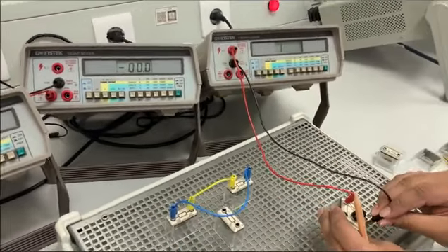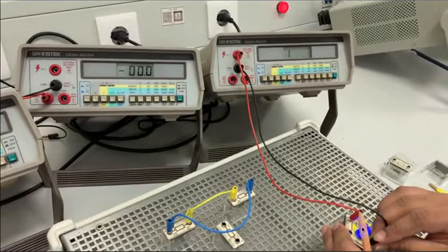Okay. Now I will use the potentiometer. This variable knob is used. It is a potentiometer. Here we can set the resistance. We can vary the resistance value. What is the total resistance value we have now? R Thevenin is 131.4 ohm.